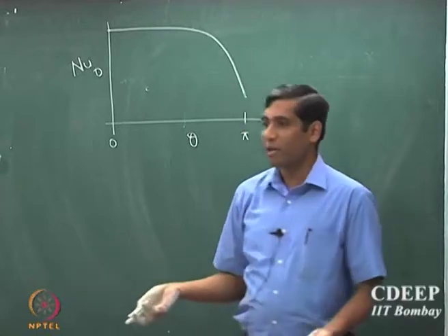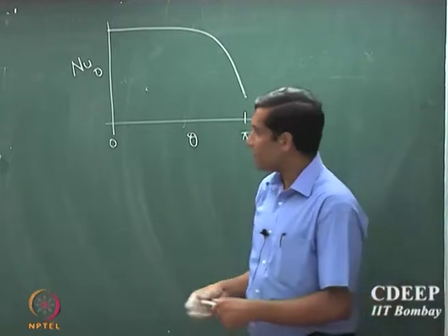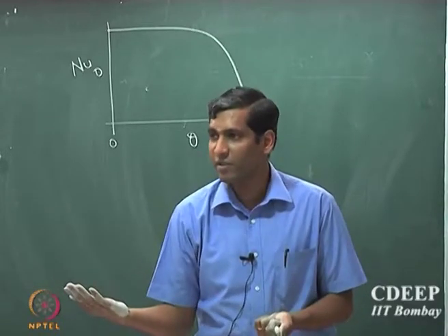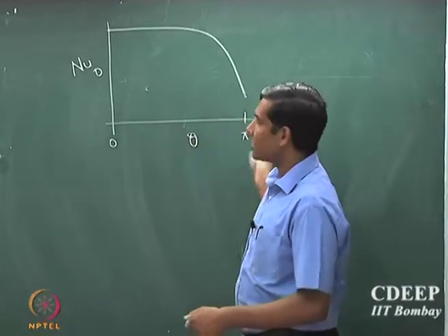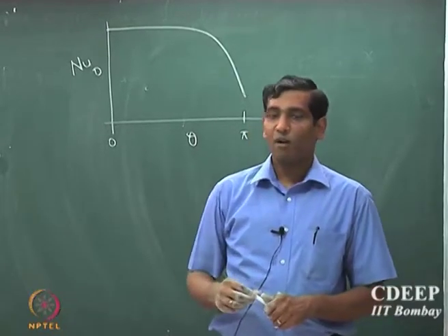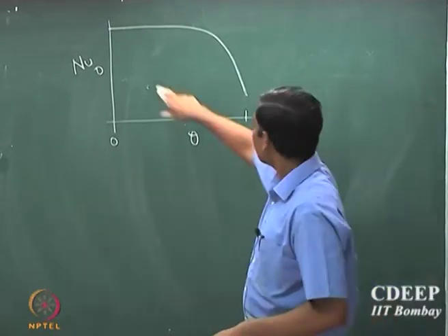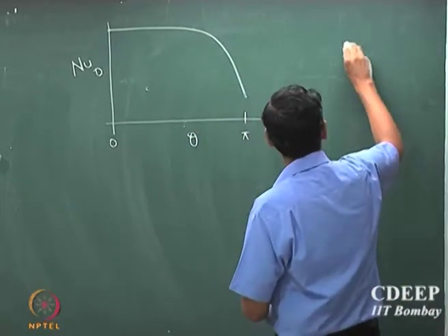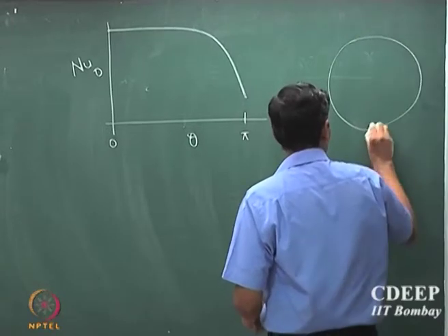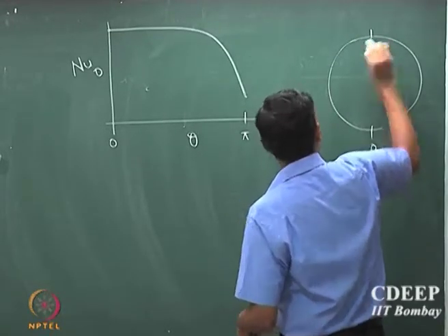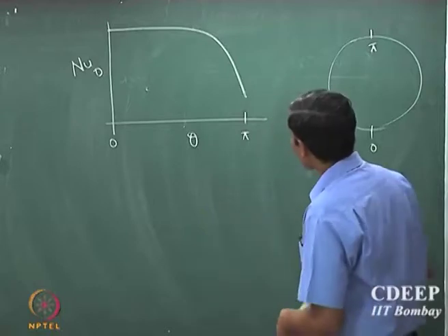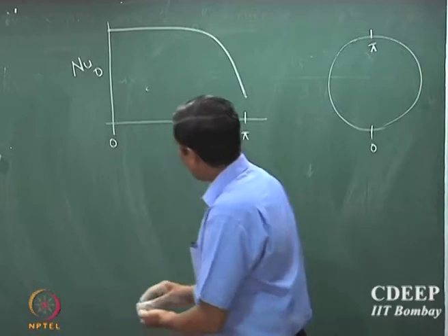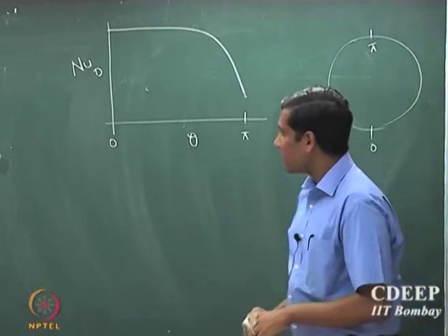There is going to be a separation point, right? When this fluid is flowing around, the fluid is no more in contact with the surface, and so you expect that the Nusselt number that you would calculate using these correlations would fall as you go close to the other end of the cylinder. Remember that theta 0 to pi goes from here, this is 0 and pi is here. Okay. So that's the kind of profile for the Nusselt number that you would expect.